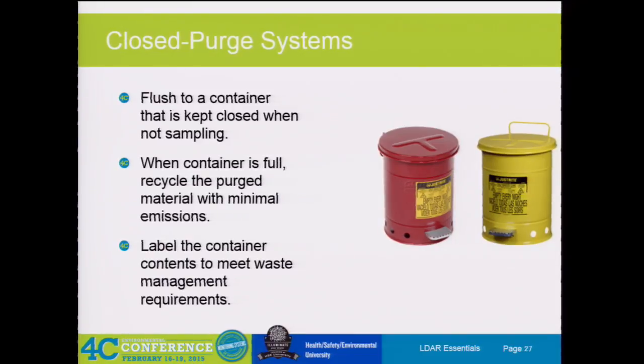So, I'm new to LDAR. You keep mentioning heavy liquid. What's the definition of that? Is it still LDAR? Light liquid and gas vapor is anything that's greater than or equal to 10% by weight VOC or 5% HAP. I thought that's the definition for being in LDAR service. Yeah.